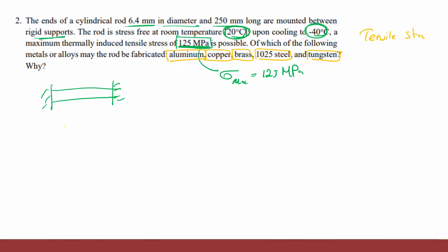So that's tensile stress we can calculate. How do we calculate thermal stress? We can calculate it as E times alpha times the change in the temperature. Do you agree with this? We already discussed this equation, how it came. So here, this is not changing for any material. How much will be the change in the temperature?